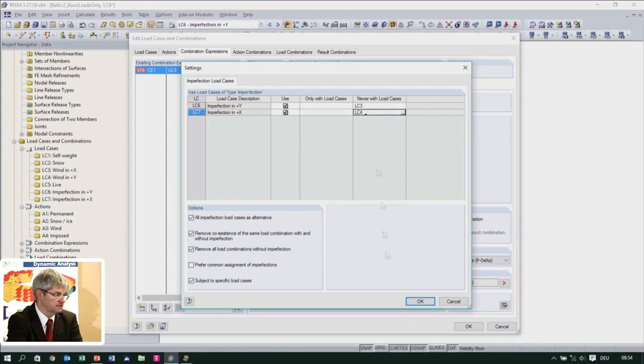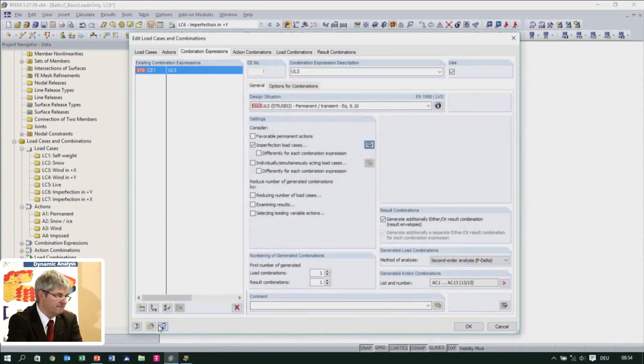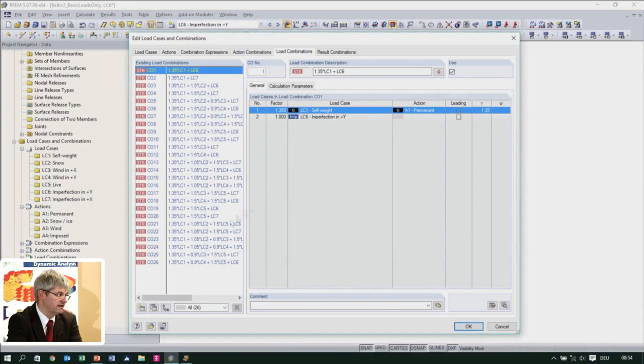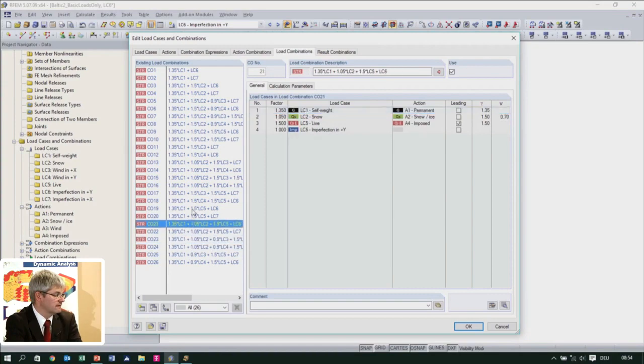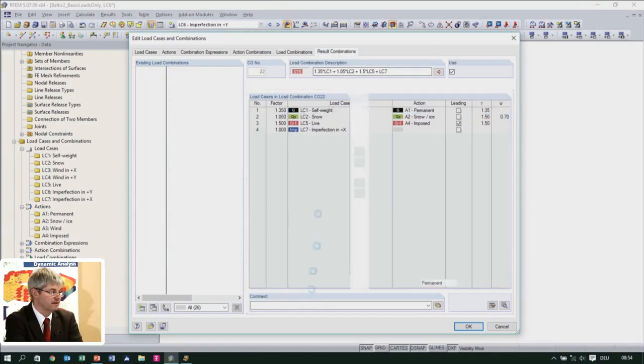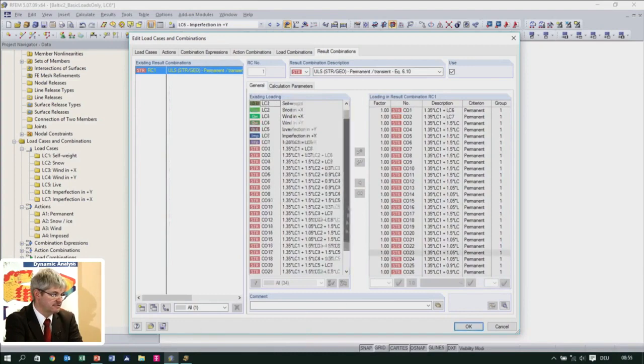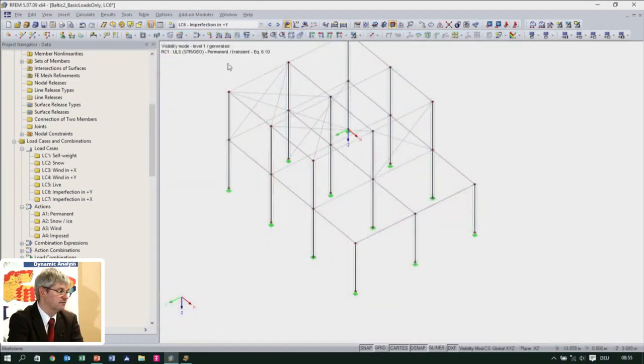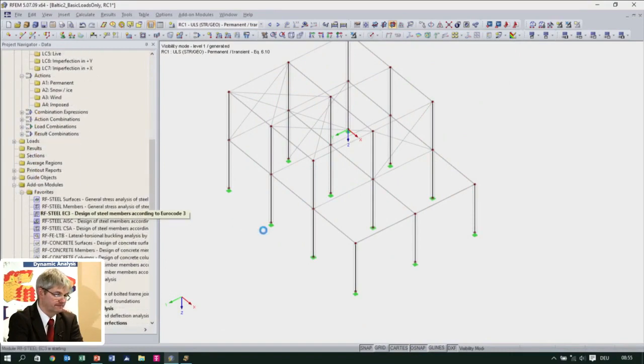And the same way in the other direction, load case 4. So when I do this, I have a different amount of combinations, and I get only 26 in this case. When there is no wind, it will use both directions. When there is wind, it will preferably use the one that is most unfavorable and most likely. Of course, there are many things we can talk about here, but this is pretty much practice from what I know from the user. With this, I have now 26 instead of 42 combinations, and I'm going to use those for the design.